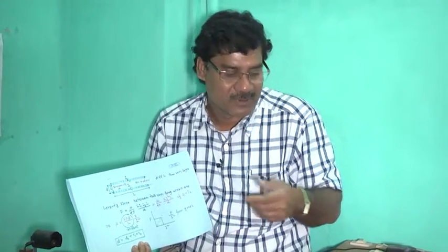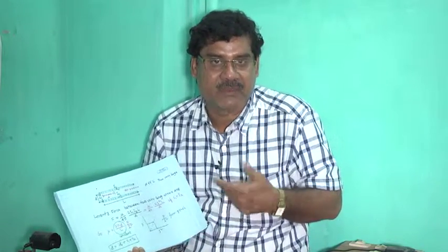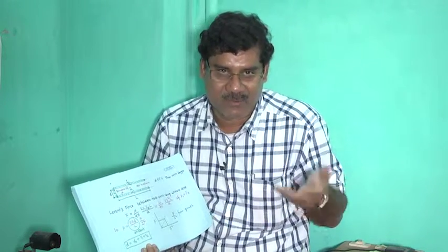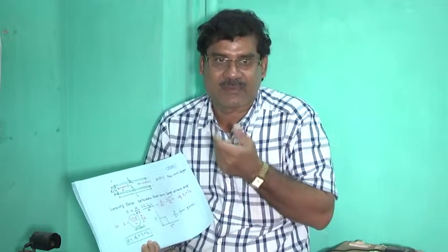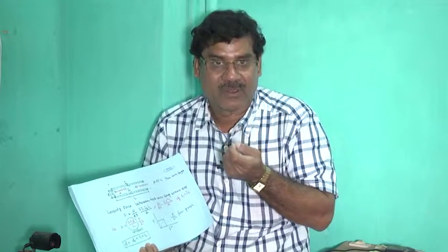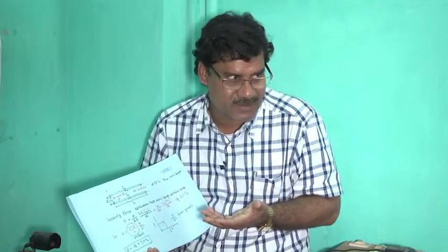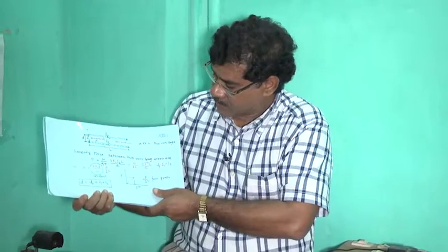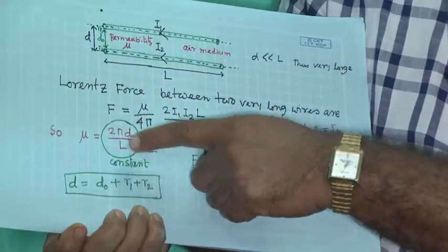So you do not need to be very cautious, because the error is delta L by L. Delta L is 1 millimeter; if L is very small, say 10 millimeter, then you have to be very careful. If it is 200 millimeter, then fine, you can casually take the reading. So D and L, that is done.